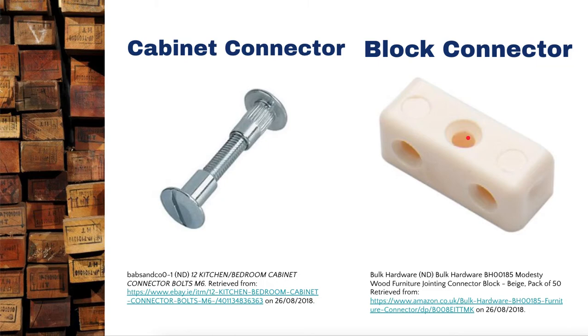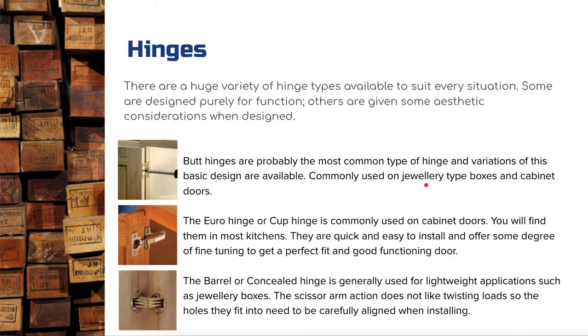Screw, so this one here is actually upside down, so that little hole there you would actually have on the bottom. Okay, but your screw goes down into the top of your entertainment cabinet to screw in, and then you put two screws in the side, which then screws into the side of the cabinet, and it holds your 90-degree cabinet together. So it can strengthen a miter joint, for example, or it can be used in butt joint applications and things like that as well. So it gives you that extra bit of strength. And these things here you can get for around about 10 cents a piece at Bunnings.